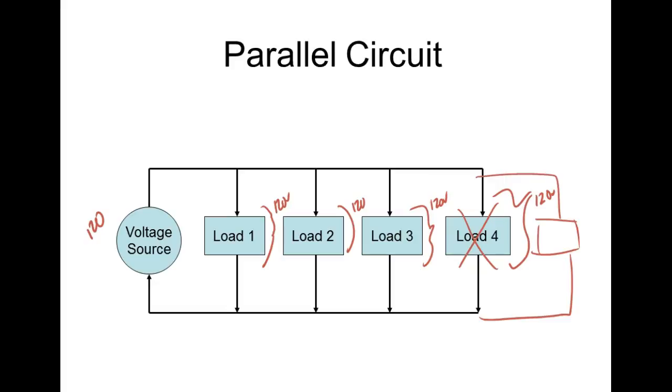Does that make sense? So parallel, this is the way power is distributed. Power is distributed in parallel, but we still have to have conductors, and we still have to figure out how we connect all of these together. If I went into my breaker box and looked on the side right here, I have one wire running out. I might have 15 plugs out there, but I only have how many wires? One. Well, what we have to do is figure out how we do all our jumping and hook them up in parallel out in the house, not at the panel.